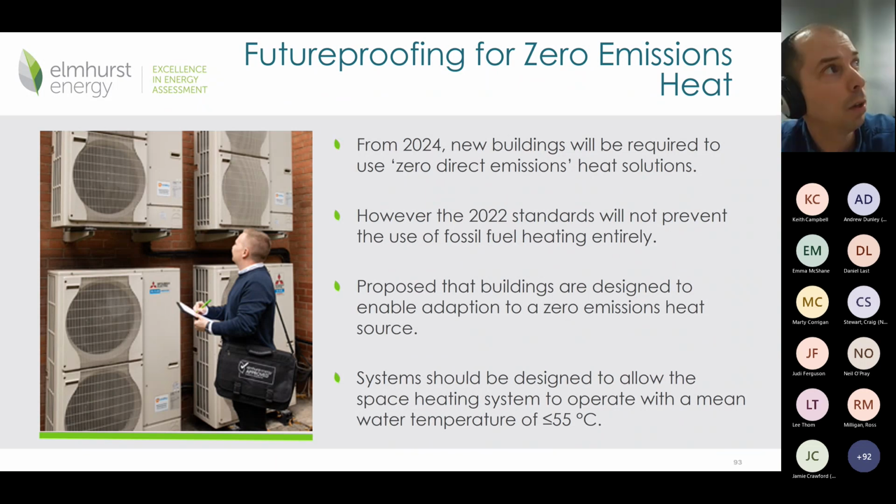There was some concern, obviously, as you bring the flow temperature of your heating circuit down, you do need larger and larger radiators if that's the heat emitter of choice. And there's a risk, actually, you could have a radiator that was so large that it wouldn't be sized, it wouldn't be located correctly in the building, and that could have some unintended consequences as well. So there is some concern about